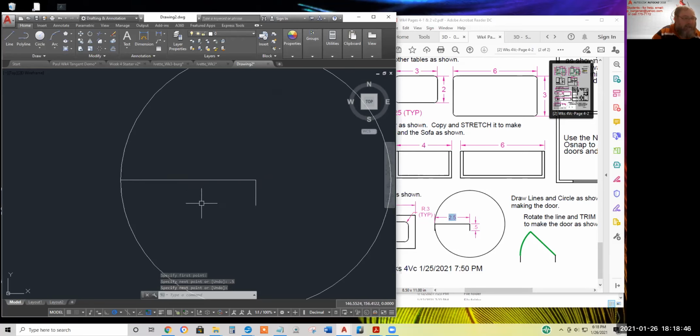Should I mirror it, copy it, redraw it? Whichever happened to come across, mirror first, enter. There. Let's rotate the door about this point, negative 45 degrees, then trim the circle away. And we'll be done with this door symbol. There's a way we could turn these into rubber stamps for economy and productivity. But I think that's in the intermediate class.